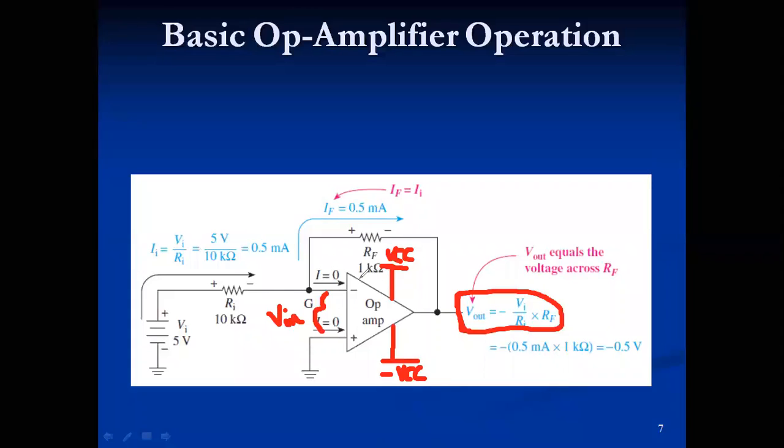If you just pull the OpAmp out without any wires, any resistors connected, no feedback. Feedback means you take the output and you connect it back to the input. No feedback loops or anything. You just have the OpAmp sitting in space, of course, connected to its power. It's just going to amplify it according to the gain A, which is a characteristic of that OpAmp. So it will be A times the difference between the 2 voltage leads.